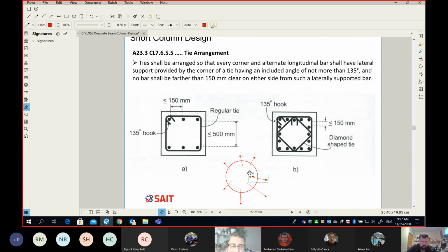Ties are fantastic when it comes to tension force. Really, they have a problem with bending because they are tiny. A 10M bar is tiny. If you remember, I mentioned your hair strand. Take one of your hair strands and try to bend it, it's easy. Try to cut it in tension, snap it, it's very hard.